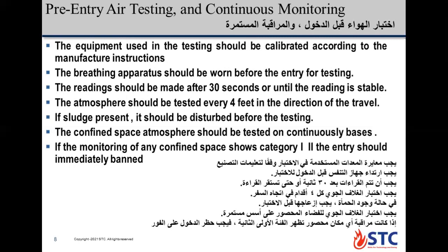In the third point, the reading should be made after 3 seconds, or until the reading is stable. To read the concentration of the oxygen or the flammability of gas and other risk.